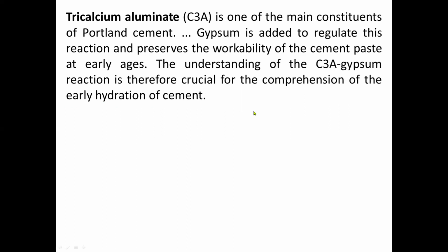It is actually one of the main constituents of Portland cement. Gypsum is added to regulate this reaction and preserves the workability of the cement paste at early ages. The understanding of the C3A gypsum reaction is therefore crucial for the comprehension of the early hydration of cement.